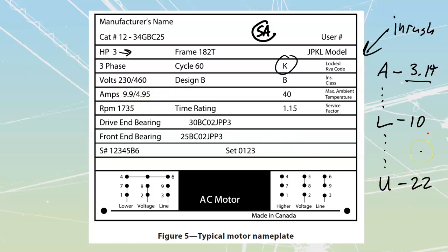It's going to be really a measure of how good of a motor builder this manufacturer is. If this is from a good motor manufacturer, like Baldor or something like that, that's recognized, WEG, some of these guys that just throw out motors day in, day out, they're going to usually have pretty decent locked rotor kVAs. But if it's going to be a crappy, low tolerance, cheap motor, then it is going to have a higher locked kVA code.